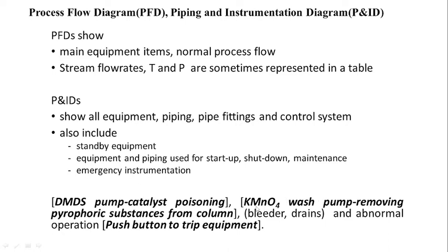So in order to prevent that, we will wash the whole reactor scheme, reactor tubes, reactor piping, everything, with KMnO4 and remove all the pyrophoric material. Pyrophoric material is denoted by FeS. When FeS is contacted with oxygen, it will release heat by forming Fe2O3. So when we contact FeS with KMnO4, it will be converted to FeSO4. This FeSO4 is less active when compared to FeS.